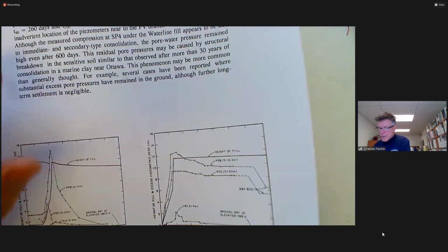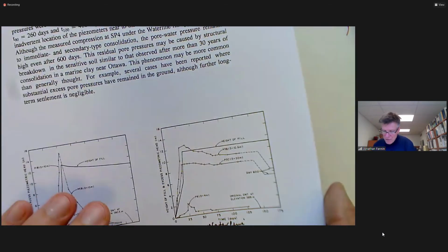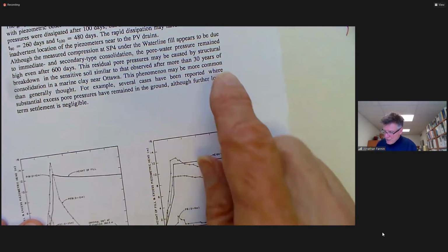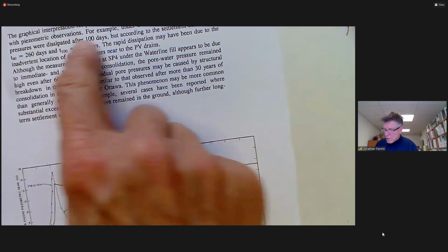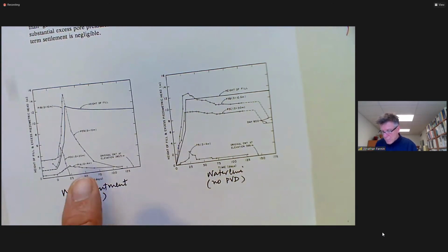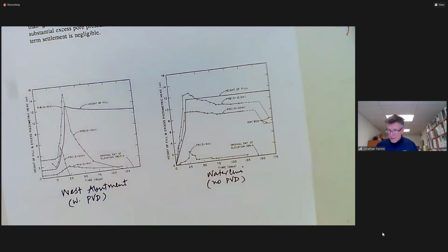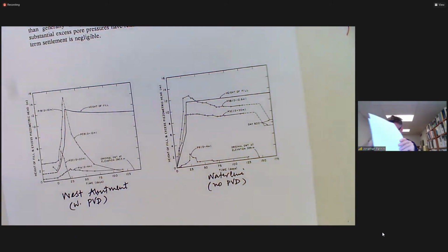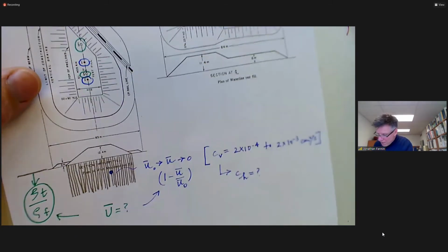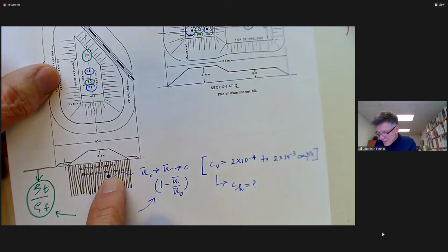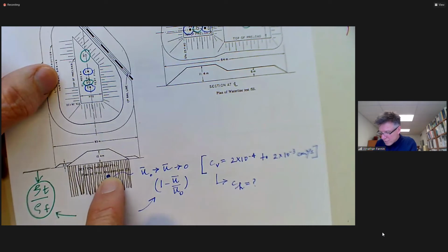And Carl Crawford had seen that in many other sites, attributed it to destructurization, and that's captured in part of the text here. The second thing is, you know, these pore pressure dissipations are relying, and let's go back to our forest of wick drains, they are relying on measurement of pore water pressure, and you have no idea how close or far away is the nearest wick drain.